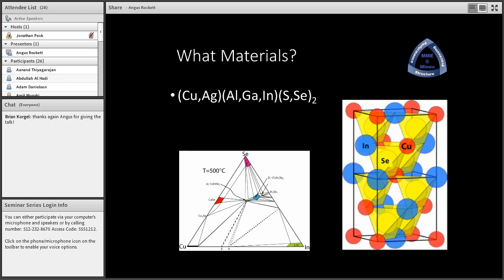And most of the deposition processes don't use really high quality vacuum, so aluminum tends to be more of an issue. But it turns out that you can actually improve the device energy gap, or output voltage, by increasing the number of alloy constituents. So copper, silver, gallium, indium, sulfoselenide, putting all of the elements together gives you the biggest increase in energy gap for an otherwise equivalent performance of device. But the best devices are copper, indium, gallium, selenide, possibly with a little sulfur thrown into the surface.